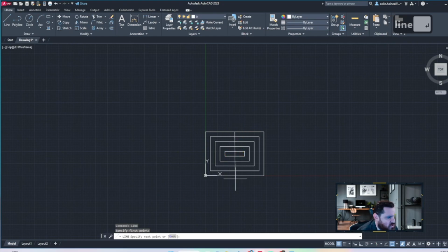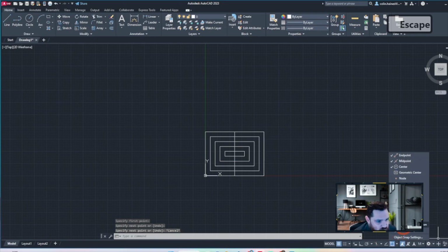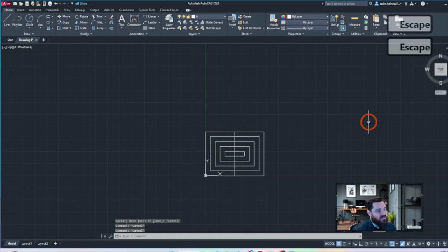And I'm just going to chop a line right down the middle. With O snaps, a triangle represents a midpoint and a box represents an endpoint. So I'm going to go all the way down here to the bottom. And pretty much what it shows in here is what it is, other than midpoints. Tangent looks just like that. Extension is a dashed line. But midpoints, for some reason, it doesn't show you the little triangle. But it's a little triangle, as you saw.